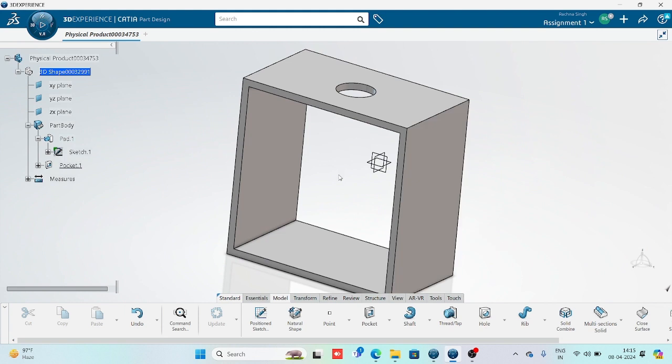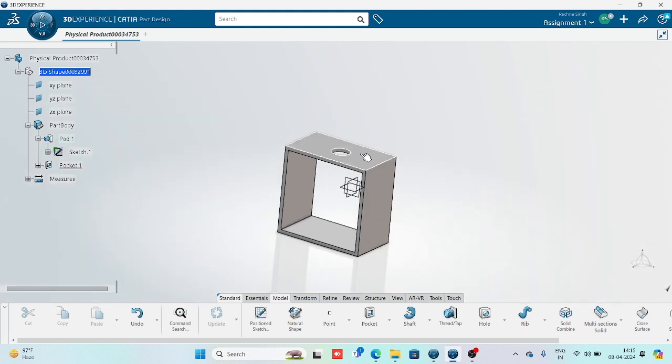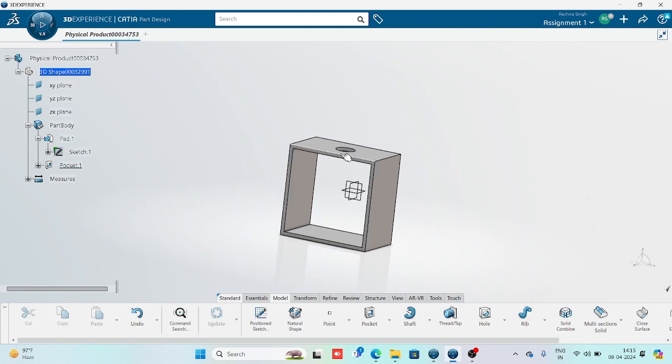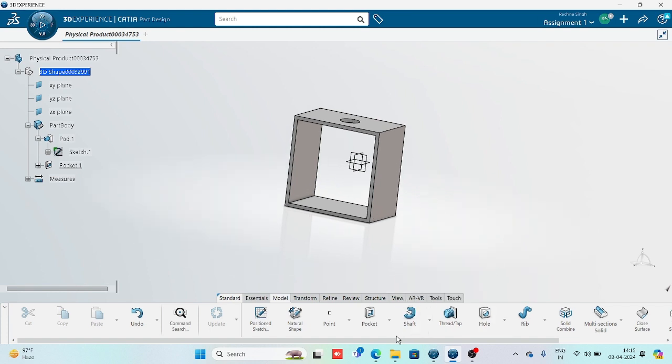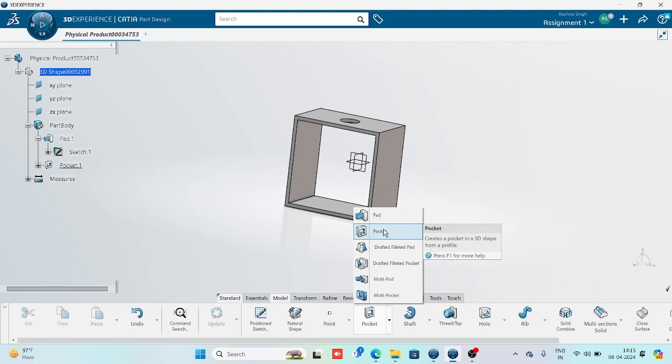But now for the pocket command up to next, the next phase will be here because the material will be removed in this area only, because here there is no material, so no work done. That is the reason it is taking up to next as this. And here you will see that up to next and up to last, the features are same.